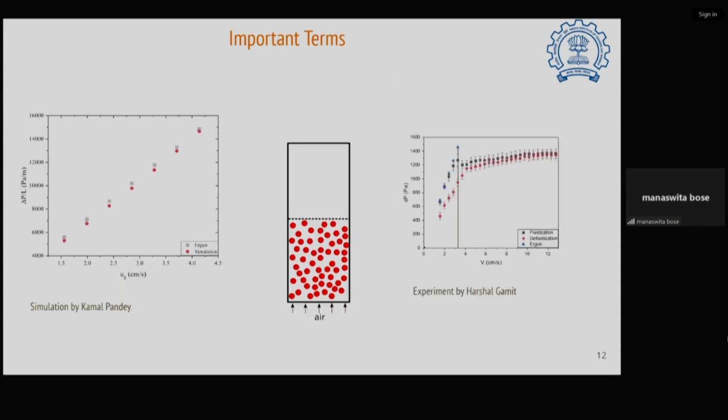Now, this is one thing I just wanted to show, that whenever we do some simulations, we also have to look at the validation, or how good our simulation is. Nowadays, mostly we are using packages. So when we say validation, it's not like earlier days where we were validating our codes. What is it that we are validating? Whether the grid is fine, whether the time step is fine, whether the accuracy or the convergence is fine.